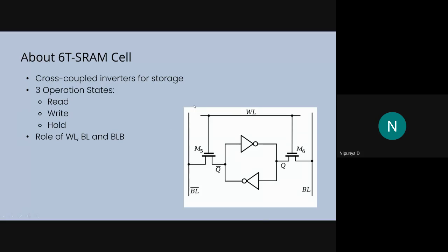How this actually works is, say you apply the input as 1 to this end of the upper NOT gate, so you will get 0 on your right side, right? Then 0 would be applied as input to this, so again you will get back 1. So it is able to store two values. It is also known as a bistable element, which is used for storage, and this itself forms a very simple latch.